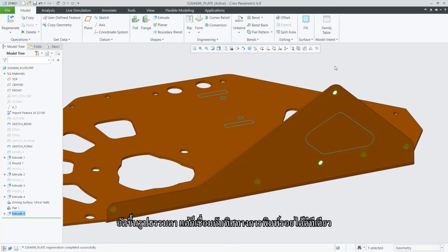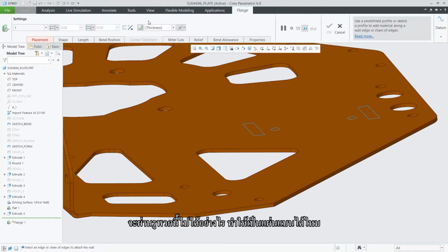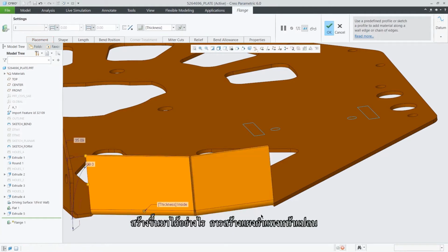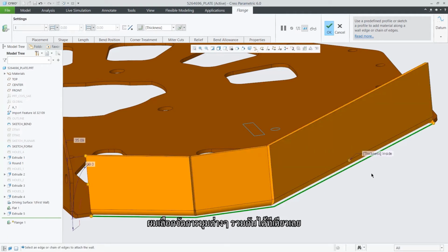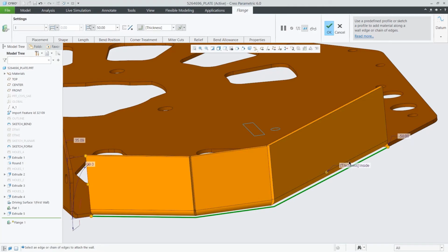They are extrudes that also understand the direction of punching. How do these holes go through? Are they laid out in the flat? How are they created? Let's create a flange wall. So for a flange wall, I can grab multiple edges and say take the whole edge, or in this case I want to back it off of that corner down there, so let's give it a value.